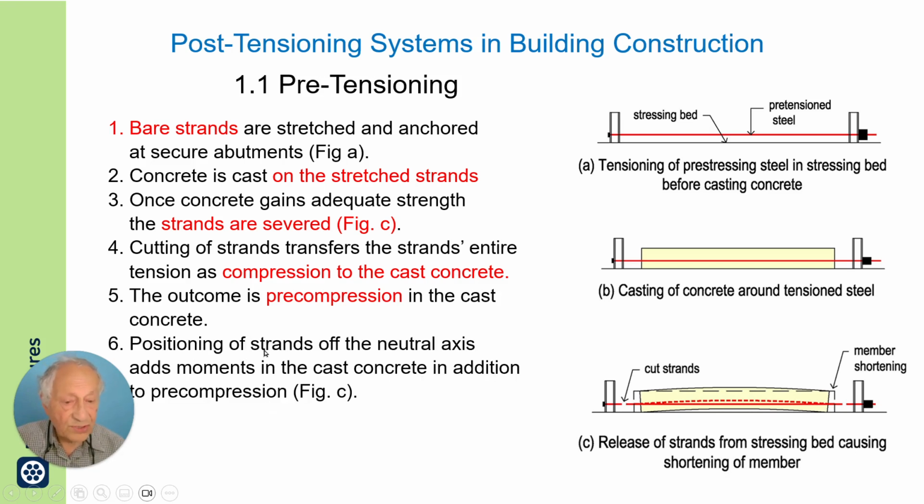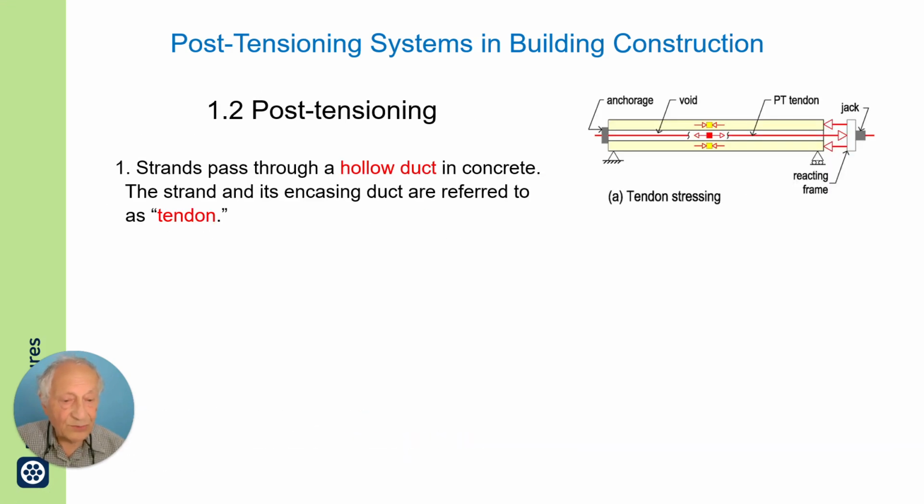Now, positioning the strands off the neutral axis, as I have shown here, will add bending moment in addition to pre-compression. And that bending moment could be beneficial if the strands are off-center the right way.